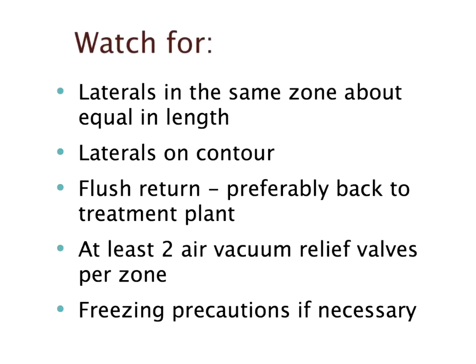Okay, what must you look for? The laterals in the same zone should be about equal in length. If you have one lateral much longer and one much shorter, your flush velocities are not going to work very well. Most of the flush water will go through the short lateral, where there's a lower frictional back pressure, than through the longer lateral. So they should be approximately equal.